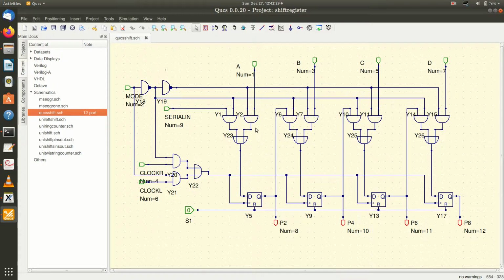Now what is it receiving? When they are enabled, the serial data can pass through this and through this OR gate and reach this D input. Now the Q output of the first flip-flop is connected to the multiplexer here, and this AND is now enabled. So the Q output of the first D flip-flop travels through this and reaches the D input of the next stage. Then the Q output of that stage passes through the enabled left AND gate of this 2:1 mux, and through this OR gate it reaches this D. And this Q output is connected to the next D through this 2:1 multiplexer.